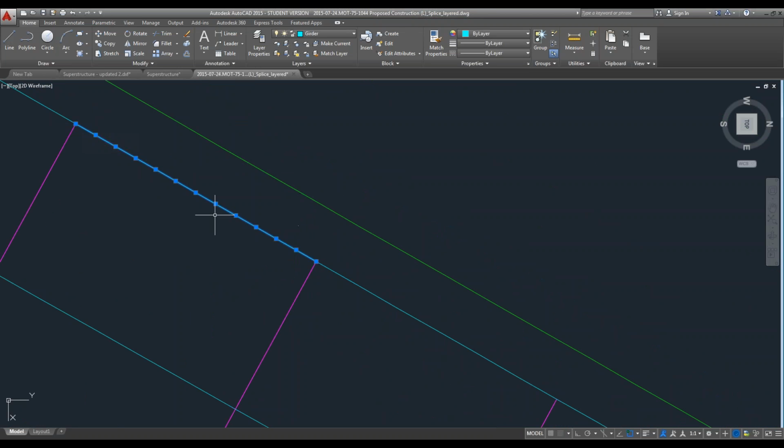And when these multiple segments are used, at each end of each line segment, that's where the node will be created. That way you can control the fineness of your model, such as node spacing along the girders, the size of the beam, or even the size of the plate when you mesh using the auto mesh feature.